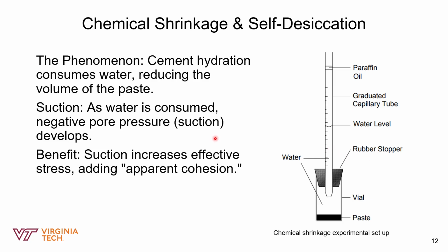Now, this matters because inside the stope, there is no extra water to suck in. So instead, it creates a negative pore pressure, or suction, inside the material because there is no extra water. This suction basically acts like a vacuum seal, so it pulls the particles tightly together.